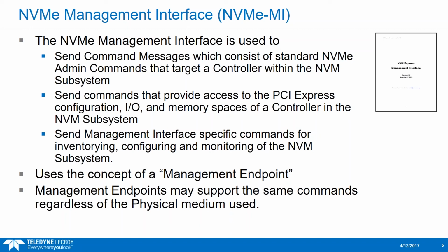Well, what happens if a PCI Express link goes down and I want to be able to read a PCI Express register from the device? Then I could do that via the management interface on a sideband interface. So NVMe Management Interface uses the concept of a management endpoint, so that's something that's on the device, and we'll see some illustration of that later.